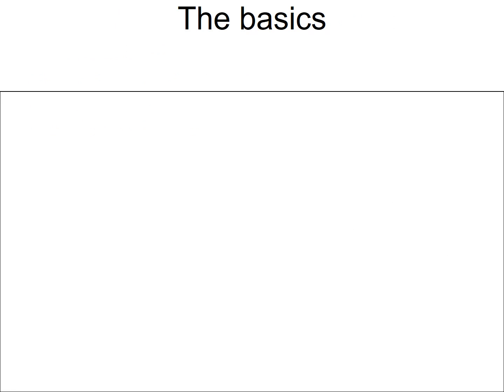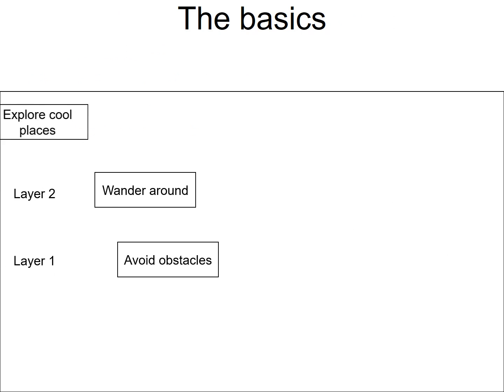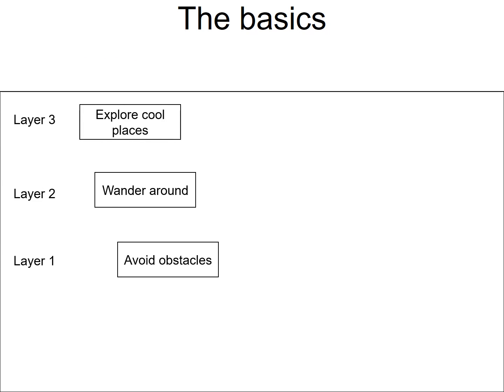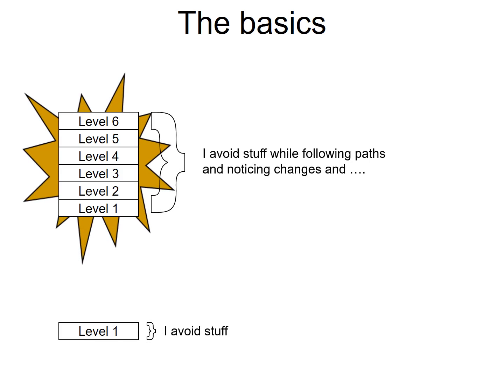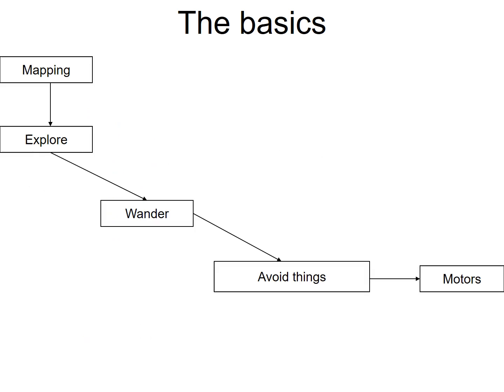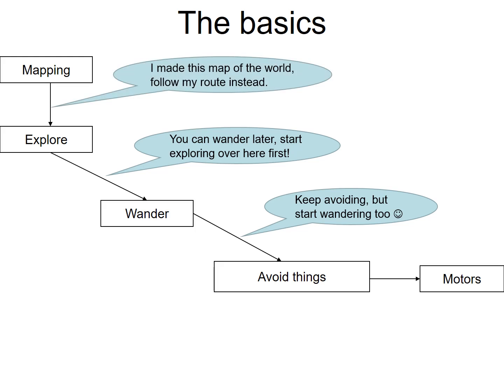The subsumption architecture is based on a number of layers, each implementing a behavior of the robot alongside the others in a hierarchy. Each layer has no idea what's going on in a layer above it, but can see the data of the layer below it, and even manipulate the input and output of the lower layer. Each layer is referred to as a level of competence, which informally specifies a desired class of behaviors. A higher competence level implies a more specific group of behaviors. This essentially means that more and more can be added to the specification of what the robot should do, with each layer being able to absorb the function of the layer below it, while adding its own functionality on top.